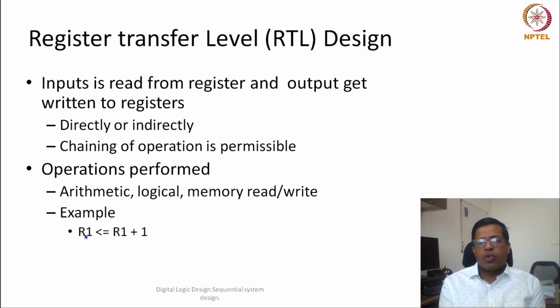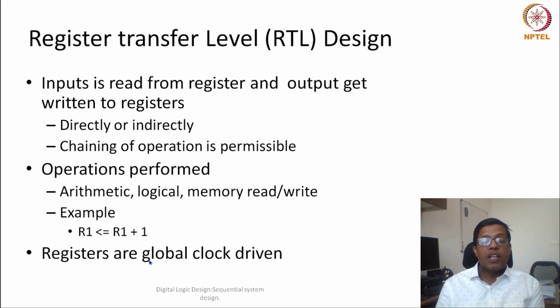This is the different characteristic of an RTL design: although such operations are defined, the latency is fixed, and the operation will be completed within one clock period, because all the registers are driven by one global clock.